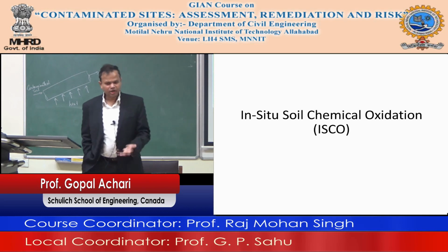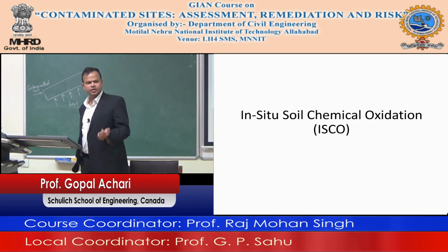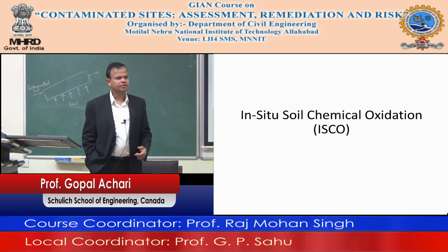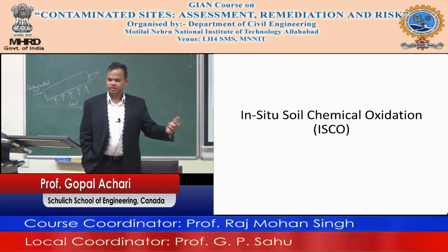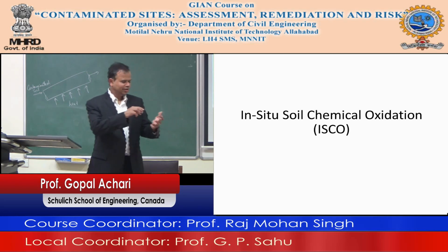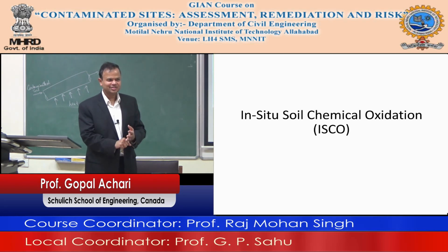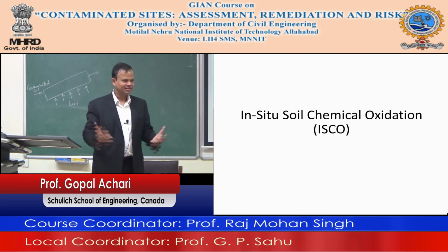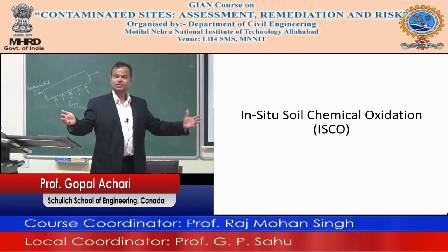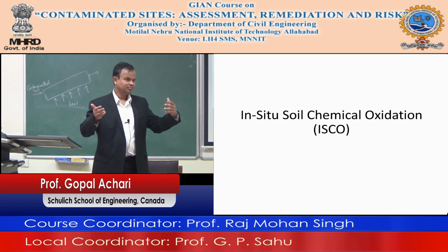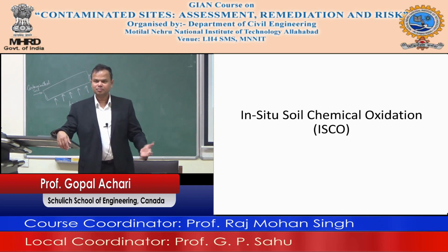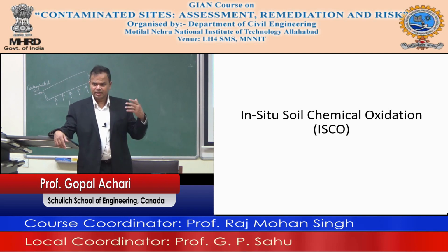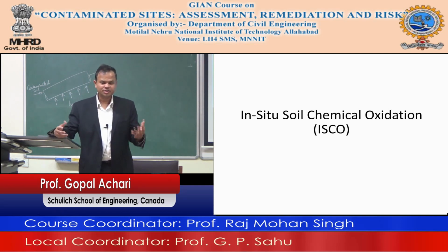So on the desorption side, you can use a direct fire desorber, an indirect fire desorber, or a screw desorber or heated conveyor. In any case you will have off gases which you need to treat. If you're desorbing something that's coming out, you need to treat it. Bottom line. And then the soil, maybe the soil is clean, maybe it's not clean, maybe it still needs further treatment. Give the example of metals and hydrocarbons. Metals may still be there, and if they're still there, you will still have to treat them, but at least you have a dry soil to treat.